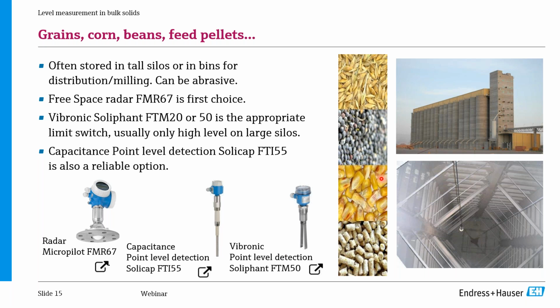Just one comment regarding the use of limit switches, especially if you have very high or very tall silos. Whenever you have this installation, especially if you're measuring, let's say, a minimum level, we always orient you guys to install a cover or protection roof, just to make sure that you avoid the direct heat of the material on the sensor's surface. So you can really improve the sensor lifetime just by using a protection roof over the sensor. Okay.